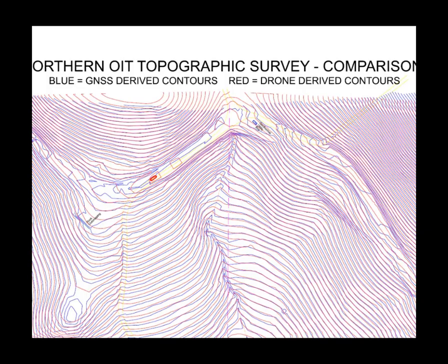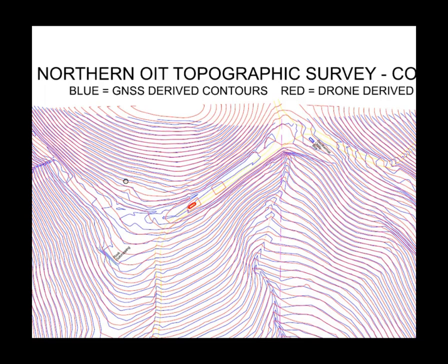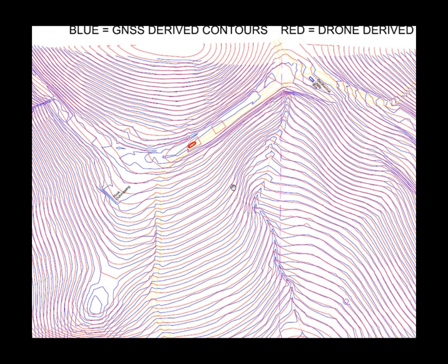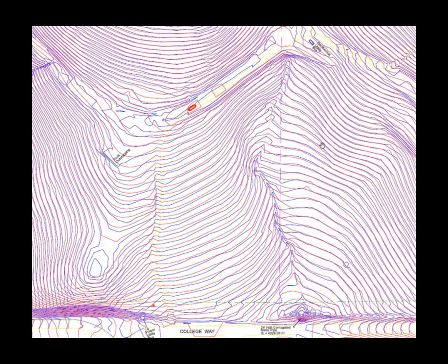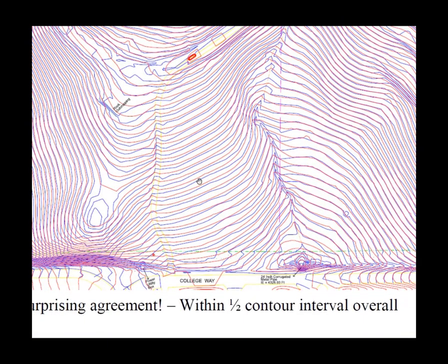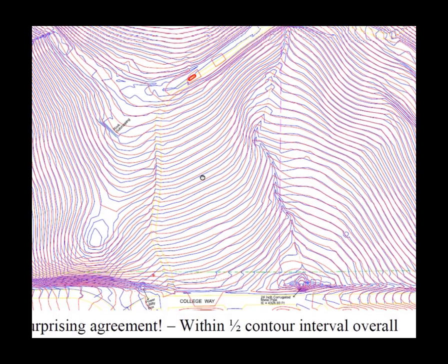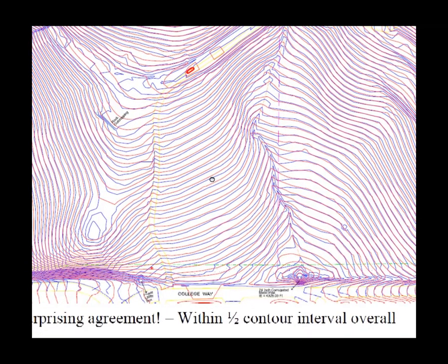As we zoom in here and scroll and pan, I didn't find any area where the contours were crossing each other from the drone compared to the RTK. We did, of course, find where there were some issues with the rock outcrop being removed. The gully was over smooth. I neglected to classify one vehicle here.